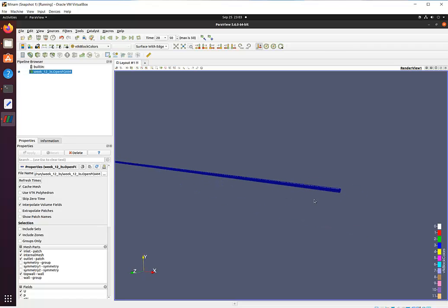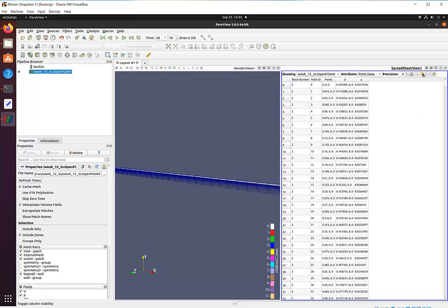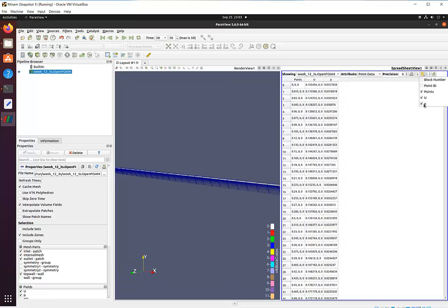Alright, if you have a look here, let's have the actual sheet view, in which let's have a look at the velocity. The velocity we see is in vector form. This is the u component, the v and w component. Of course, the v and w component will be 0, as our velocity is only in the u direction and it is laminar in nature.